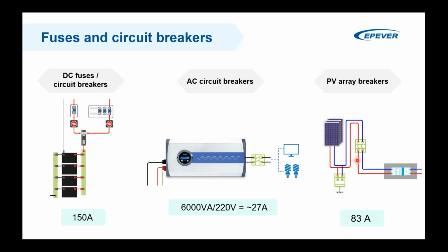And again, for the PV area circuit breakers, we have a sort of isolator. If you see here, this is the isolator, and this can be an isolator, this can be a circuit breaker or whatever. It's also the same here, as I mentioned. This is to disconnect your battery or your solar system for maintenance purposes or replacing equipment.